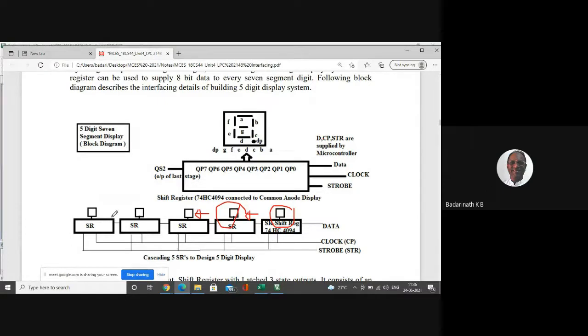So now we will develop a program. It's called a device driver program. Whenever in an embedded system at the low level you write important code like this, pushing the data into shift registers, driving the displays, it is basically called a device driver program. These are the device driver programs which are available for an operating system to invoke to get the work done through your application calls. If you see any other device driver program, this type of small code will be present inside that one.